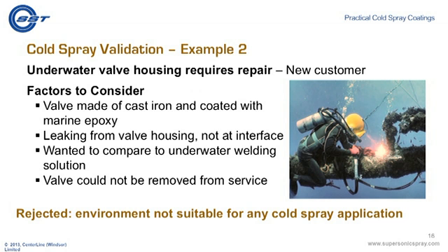We had a new customer contact us, and he wanted to repair an underwater valve housing. Typically, he's using underwater divers equipped with marine welding technology. The valve here was made of cast iron and it was coated with marine epoxy. There was leakage from the valve housing, but not at any particular flange interface. Customer wanted to compare cold spray application to his current underwater welding solution, and this valve could not be removed, repaired, and placed back into service. It had to be repaired in situ.